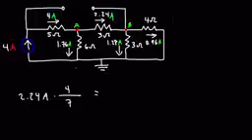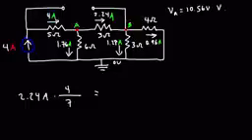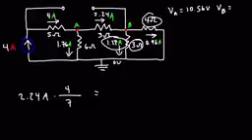So to calculate the potential at point A, where the ground is set to 0 volts, it's just going to be 1.76 times 6. So the potential at A with respect to ground is 10.56 volts. And the potential at B with respect to ground, you can multiply 1.28 times 3 or 4 times 0.96.